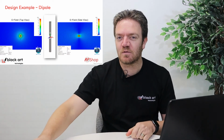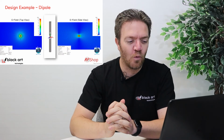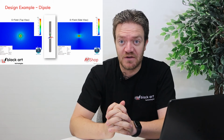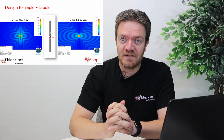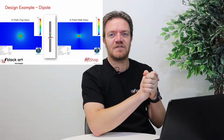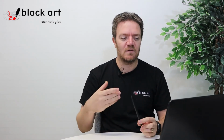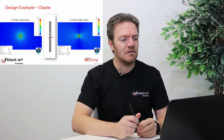Now, the beauty of tools like CST or any of those 3D simulation packages is you can look at all sorts of behavior and characteristics. If you can't measure it, how do you know? But in simulation, you can at least study it completely, and that's the beauty of these things. So with the plot that I have here, I show E fields, so electric fields, because this thing has an electric field and a magnetic field, and this is the electric field that I'm looking at, and that's the one I always use, so E field.